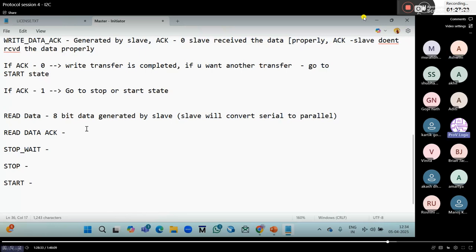Did you understand? No, if I have a sensor sending data to the I2C master, meaning it is reading from the sensor, the only way of communication is serial, correct? Bit by bit, the sensor slave will be sending to that microcontroller.